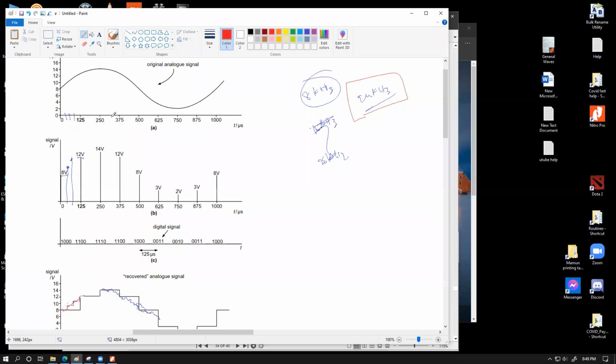This is only because of sampling frequency, but there is a catch. The catch is, if you increase the sampling frequency, you would simply be producing more data. For example, for 8 kilohertz, you are producing 8,000 instances of data every second. For 24 kilohertz of sampling frequency, you are producing 24,000 instances of data every second, which means if you keep everything the same, simply increasing the sampling frequency from 8 kilohertz to 24 kilohertz will make your file size triple.